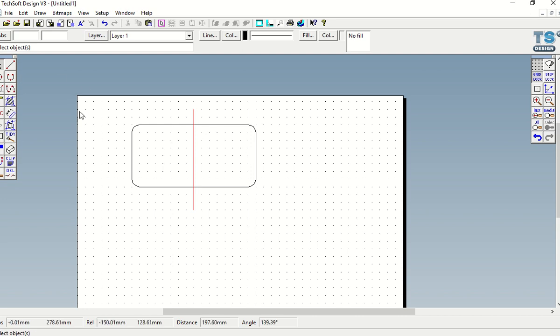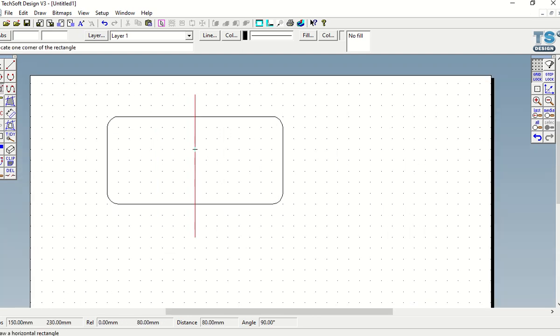So first of all, I'm going to draw a 7-segment display. They come out at 13 by 20 millimeters. Now, of course, gridlock is no good for this, so I've got to go on to step lock. I'm going to go on step lock, and again, look down at the relative. And what do we have? We have 20 by 13. That's what we want, and now I've got to place that.